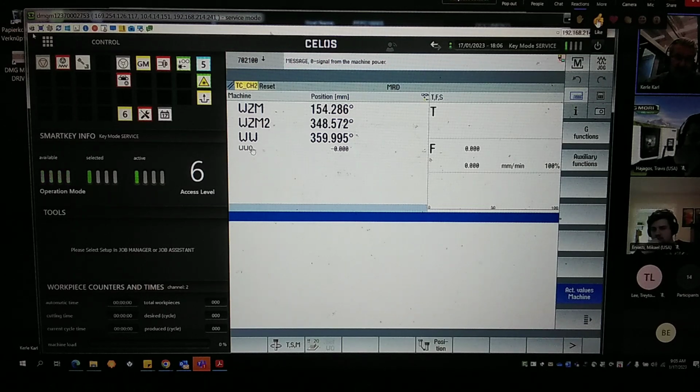Why? What's the big difference between main and auxiliary axis? The big difference is that an auxiliary axis is only used a small time during a tool or pallet change, and an auxiliary axis has only a motor encoder installed, no direct measuring system in use, okay?